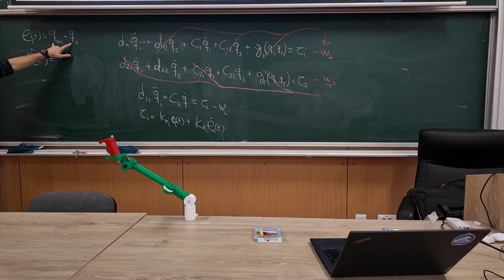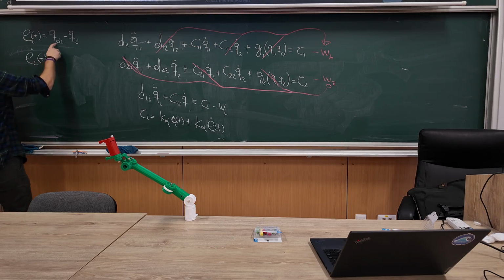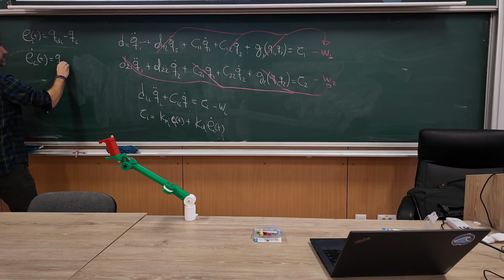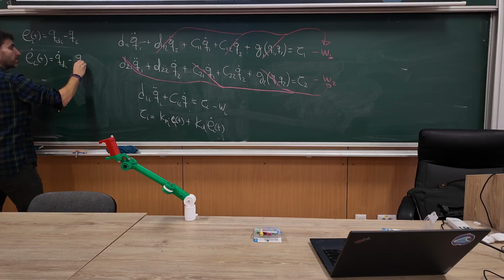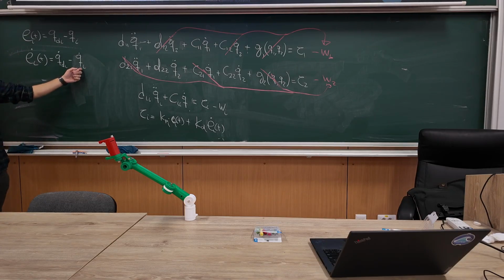would be this divided by the time difference over dt, which then it would be this divided by the time difference, this divided by the time difference. So then in the end it will be q_d dot minus q dot. So the joint velocity and the reference velocity. Okay. We'll assume, since we said especially that we have slow motions, that this is 0. So we're talking about, I don't know, a step reference where the velocity is 0, so it doesn't change over time, not a varying thing, right? Just to keep things more manageable.